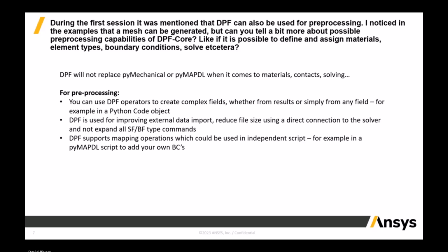Yes, basically what may be easy to remember is that PyDPF or DPF does not currently enable you to write input files for Ansys solvers. That's where you use PyDyna, PyMAPDL, and things like that. So anything you would see in an input file, like normal commands, like definition of element types, boundary conditions, and such, we do not do via DPF.